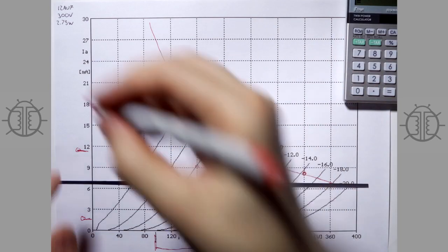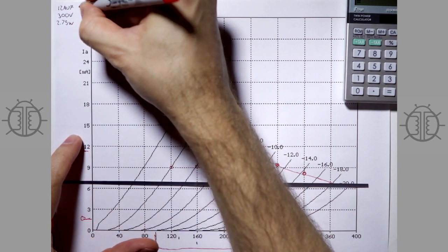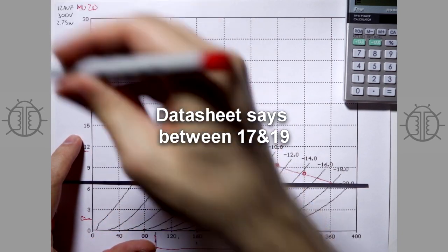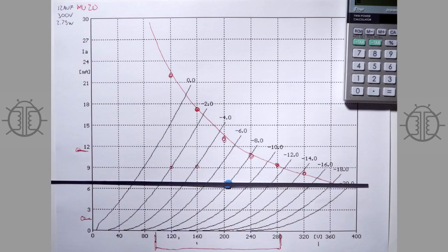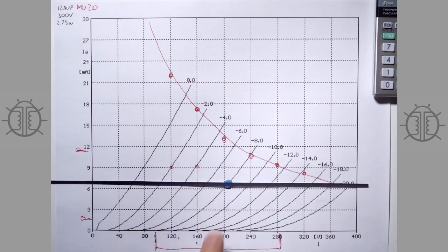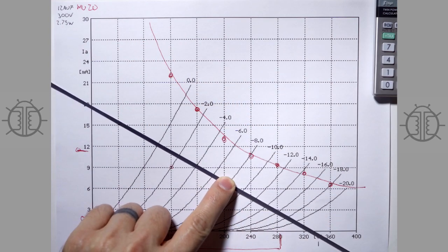And so you can see that this 12B7 has a mu of 20. And if you look in the data sheet, well, that's not exactly correct maybe, but every tube is different, and these are obviously curves that have been taken off somebody's tube in somebody's curve tracer. But you can definitely see that's what we're getting here. We're getting a voltage gain where 2 volts nets us 40 volts, right? So that's the gain.